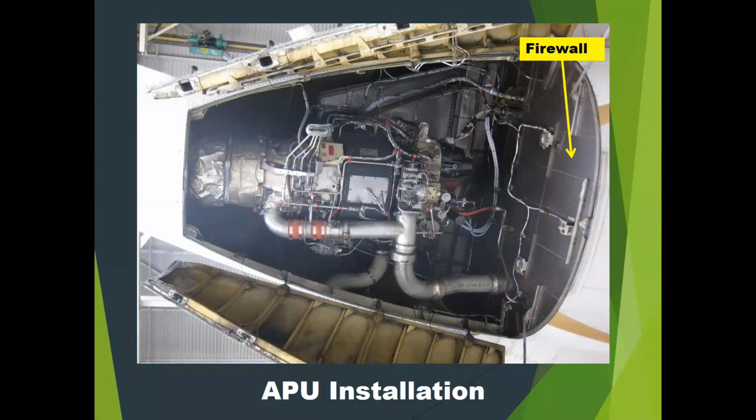Here's that same setup looking from the back, that APU enclosure. And this is showing the removal process they're using, in the industry known as fishing poles. Can't imagine where they got that name. But these two poles clip up on each side of the APU, and they have a cable that hooks to the APU.